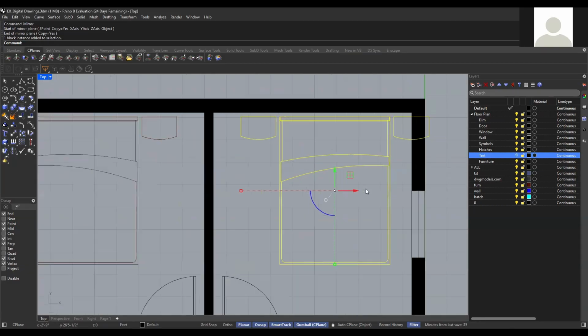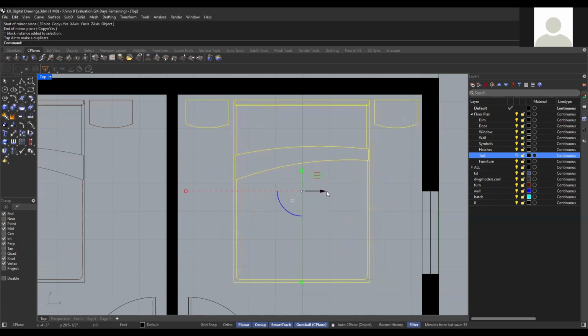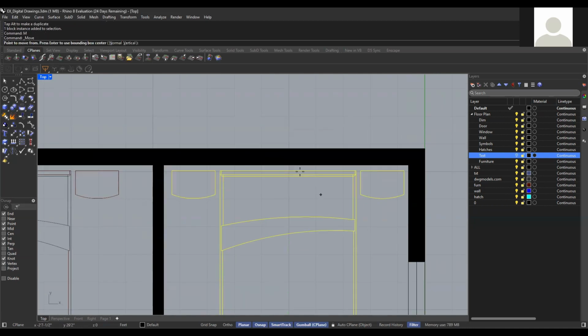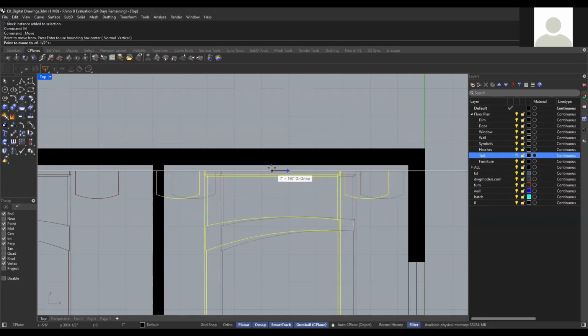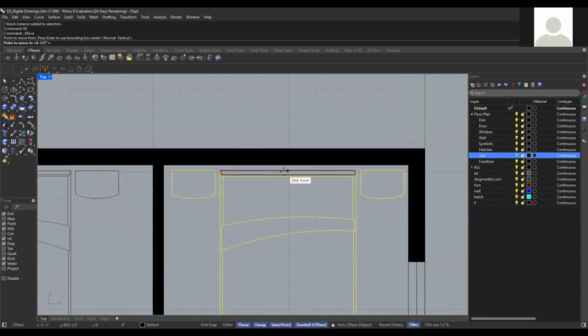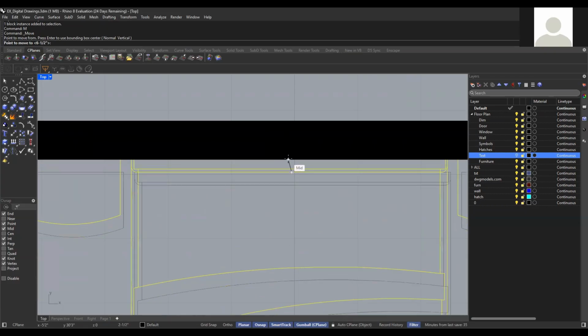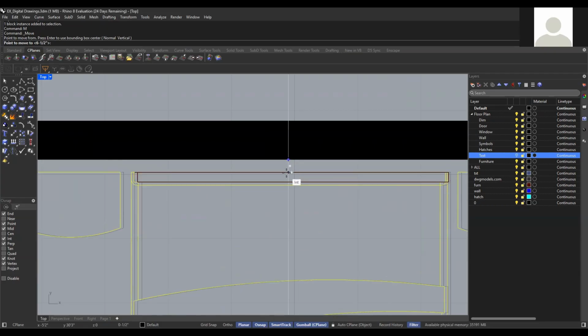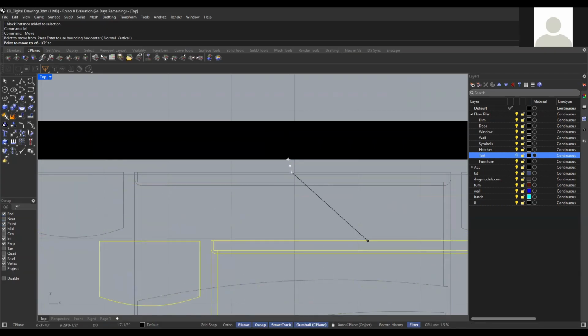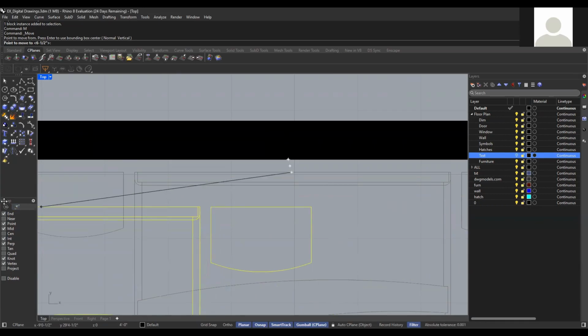same. Okay, so I'm going to move this a little bit here, or even find the mid of the bed and align it with the mid of this wall. If you find this point, you can see the axis, this white line. You may have to make sure that your Osnap is all checked, like end, point, mid, and perp. These are usually the ones I work with.